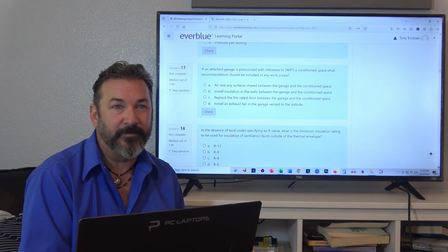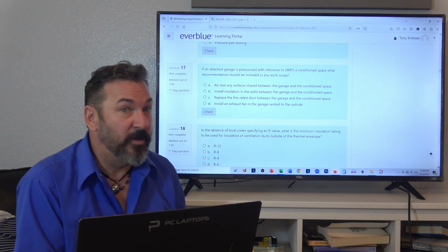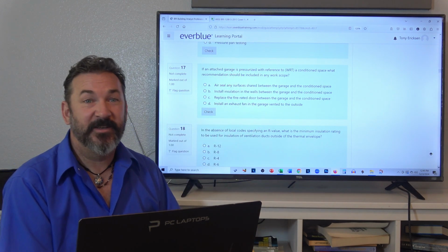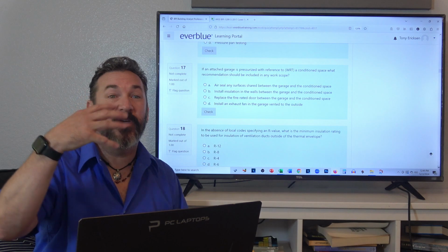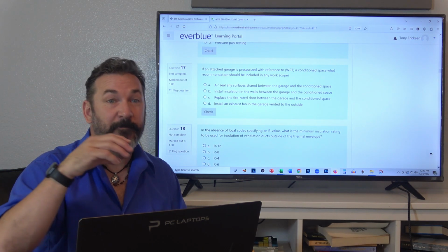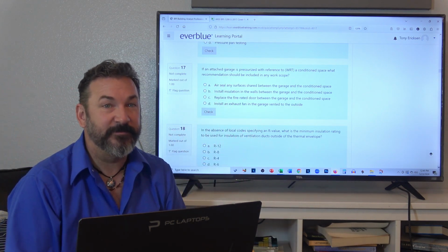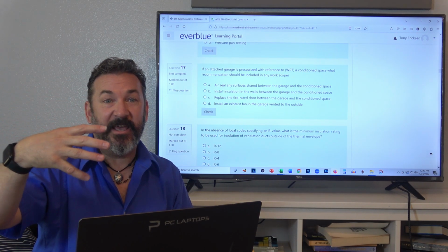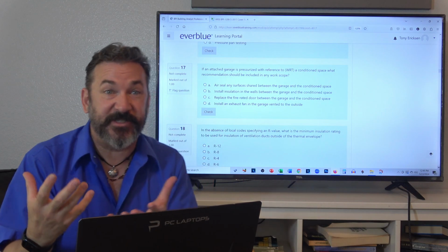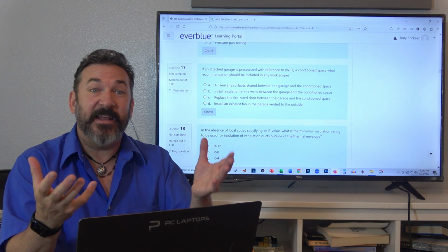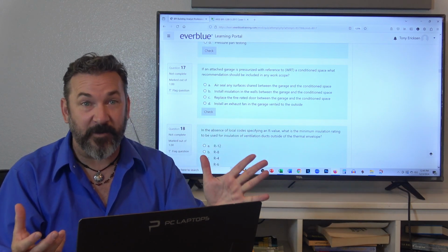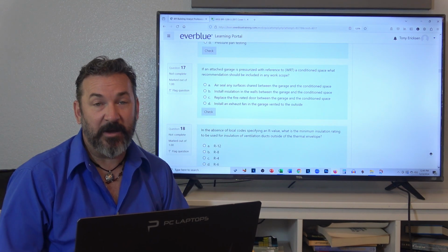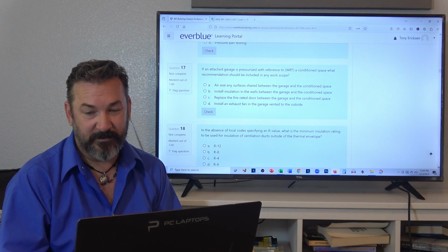What if the house is leaking air into the garage, then the exhaust fan would... That's okay. The garage is pressurized. So that means if the garage is more pressurized, there's more air pushing it into the house. So if you just put more exhaust into the garage, if you were to overcome the pressurization of the garage and made it a negative pressure, now it's pulling air from the house. Either case, you want to separate it from the house. That's true. Now it's wasting money. It's pressurizing the house.